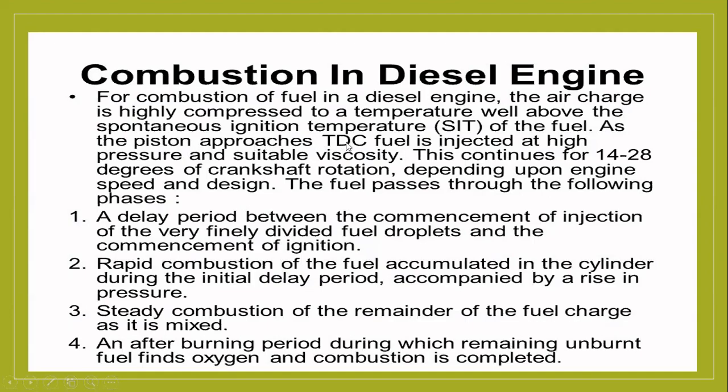As the piston approaches TDC, I told you, the end of the compression stroke, top dead center, fuel is injected at high pressure by the injector pump in the diesel engine. The injector needs high pressure and suitable viscosity, right? That's why a diesel engine doesn't work on petrol. Suppose you have a diesel vehicle and diesel is difficult to get, then you put in petrol, it will never work, right? Because the viscosity is different. This continues for 4 to 28 degrees of crank rotation. I will teach timing later.